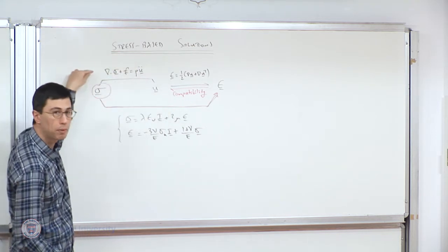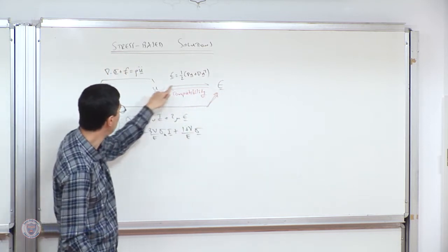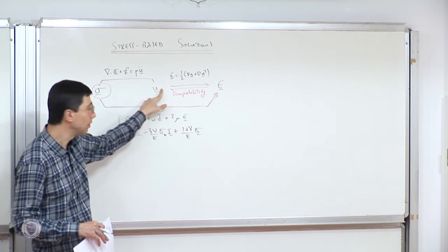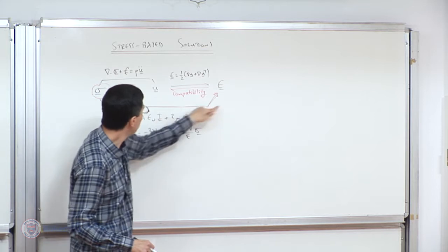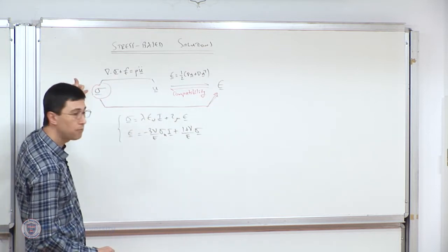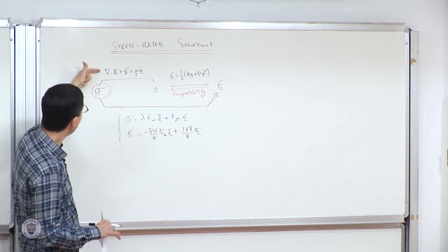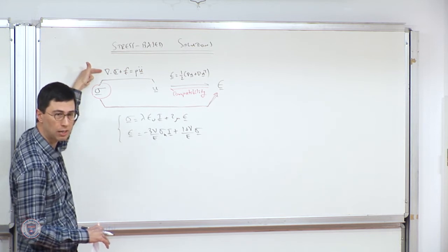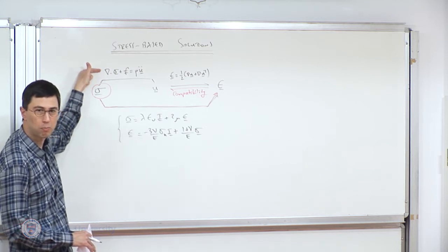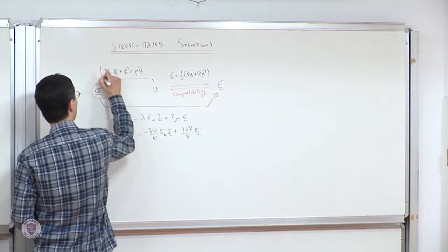But what happened to equilibrium? Equilibrium is never in the loop anymore, because I start here. Once I enforce compatibility, I know that there's a displacement field. And in fact, I will be able to solve for it. But my loop is not a full loop. It finishes here. So it turns out that in this approach, when I start with the stress, from the outset, from the start, I need to ensure that this is satisfied. And that is one quite difficult part, actually, with the stress-based approach. I need to make sure that equilibrium is satisfied from the outset. That's a critical point.